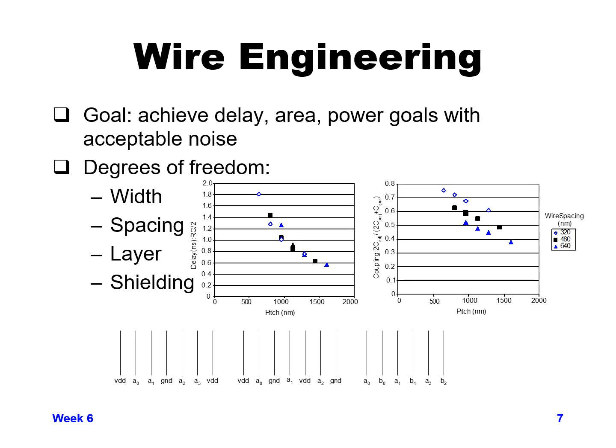So you can't use this in most of the areas of your design because you'll generally need more signal tracks than just every other track of your design. And then finally on the right hand side we're showing where you have no power tracks, all signal tracks. This is potentially the most noise problematic, but if you have some knowledge of your signals, you can use what's called logical shielding.